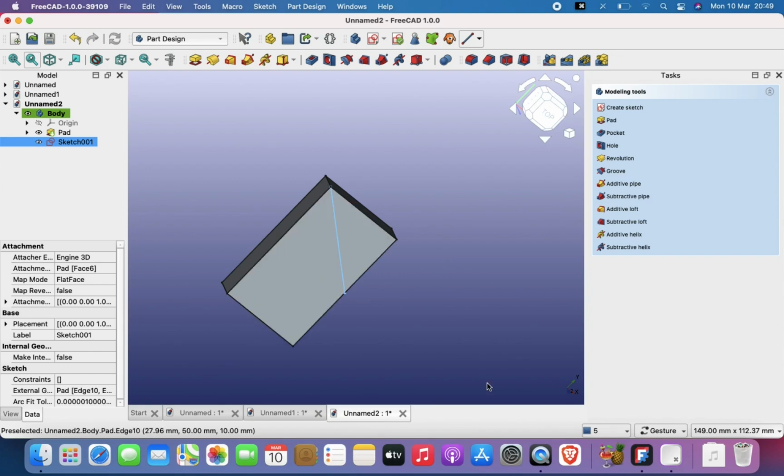Whenever you get a "wire is not closed" error, it means that your lines do not form a continuous shape. For some reason there is a broken or an incomplete line in there somewhere. So for instance, if we ask FreeCAD to cut this object, in our minds we wanted to cut this part of the object, but how does FreeCAD know that you want to cut this part? How does it know that you don't want to cut this part? How does it know that you don't want to do something different with the line? So you have to define exactly what you want to do.